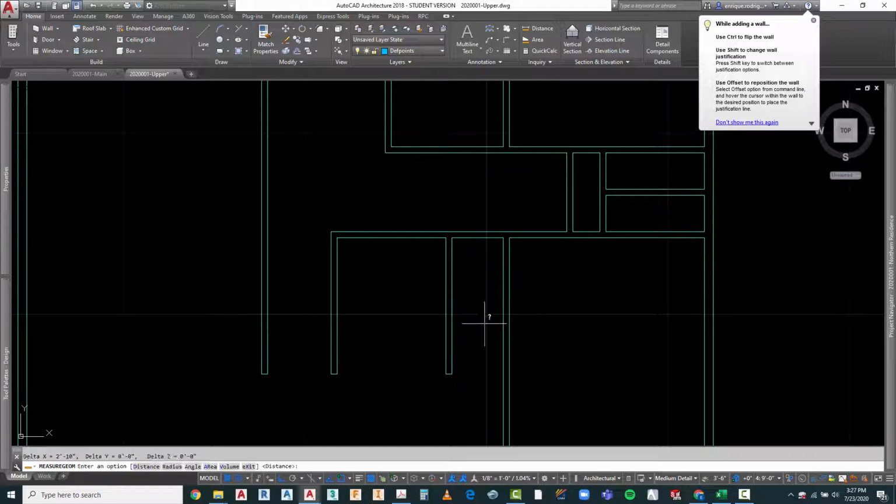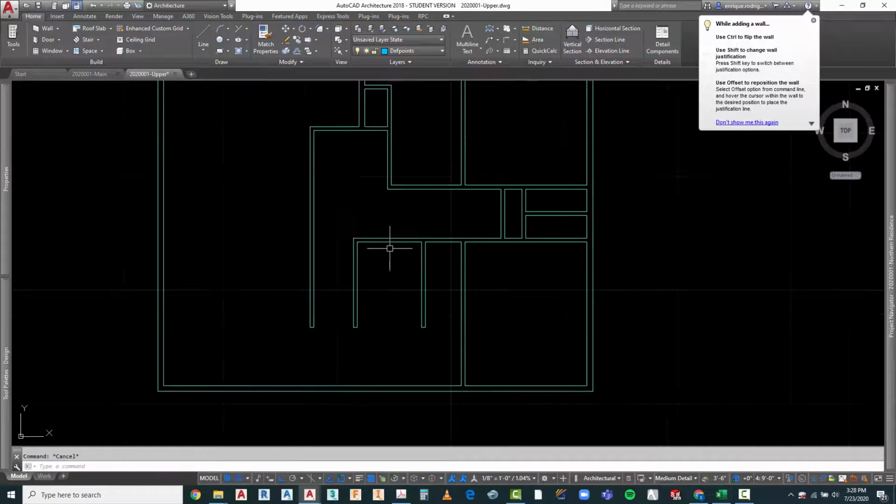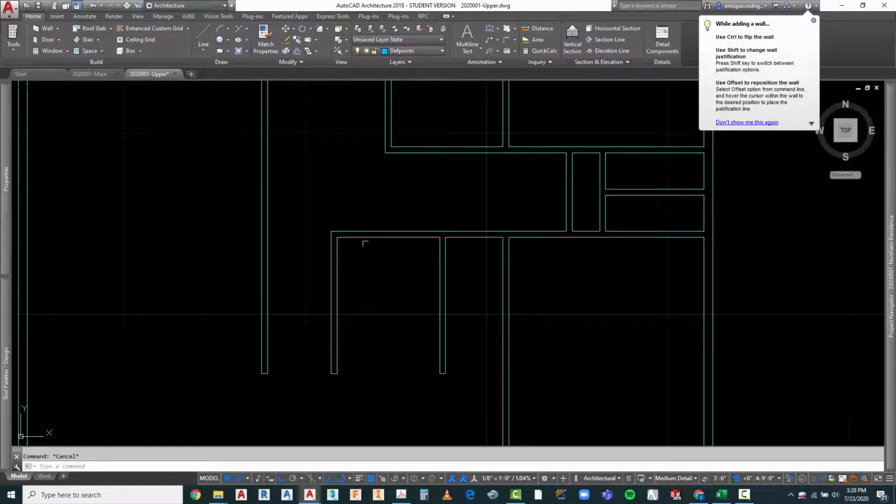Now that only leaves 6'10", and that leaves a good area right in here, which is 6'0" inside. We really don't need that. We're going to have a bidet and a toilet in there. We can really get away with about 5'8", 5'6". So for now, let's go ahead and move it over 4 inches. And that gives me a shower of 3'2". We could even make it a little bit less. All right. What's more important is where the front of that bathroom is going to be.